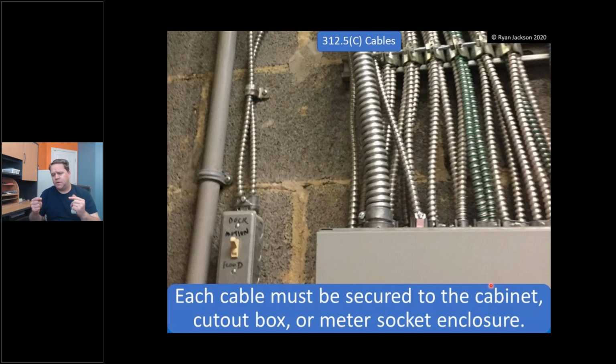Now, a cabinet is the enclosure that you put a panelboard in, right? The panelboard is the guts, the bus bars where the breakers go in. The cabinet is what the panelboard goes into. You also have meter socket enclosures in 312. That's easy enough, right? That's where the meter goes. And then you have cutout boxes, which would be like a fuse disconnect where you cut out the power.